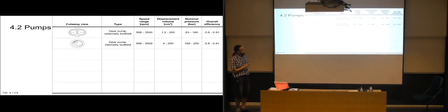The thing is, if you look at these cutaway sections, so here you have two teeth being connected. So in the middle here, there is contact between the walls of two of the teeth. They're pushing at each other. So you have just the contact of two teeth. But if you look here, you have actually quite a few teeth that are in contact with each other on the internal and the external ring. So here you can get 3, 4, maybe even 5 teeth that are in contact with each other, which means that you have a much larger area to sort of place your forces on.